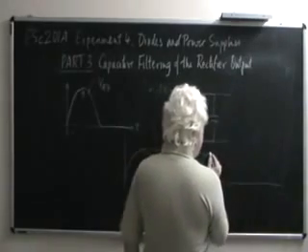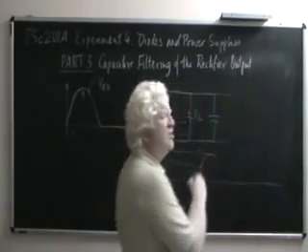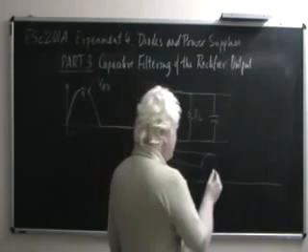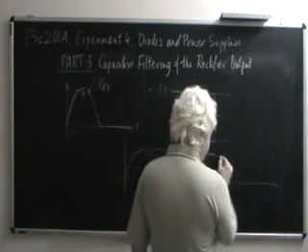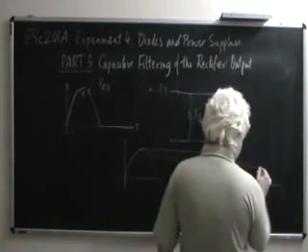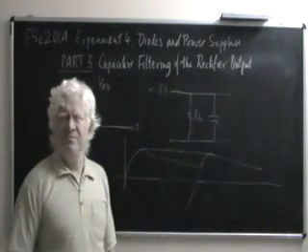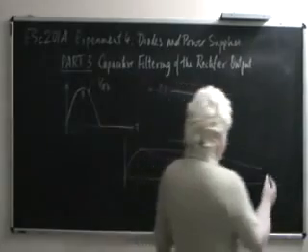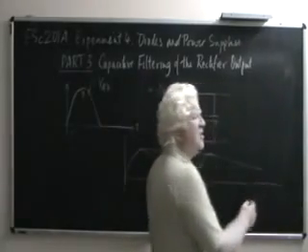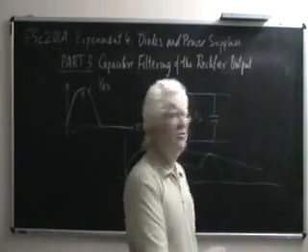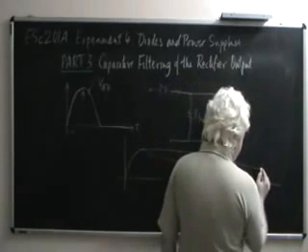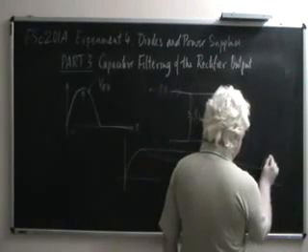In the second cycle, again the capacitor voltage droops because it discharges through the load resistance, and you get this. Again at this point, the rectifier input voltage exceeds the capacitor's voltage, and so the diode gets forward biased and it charges the capacitor.